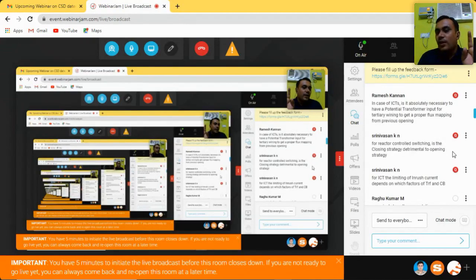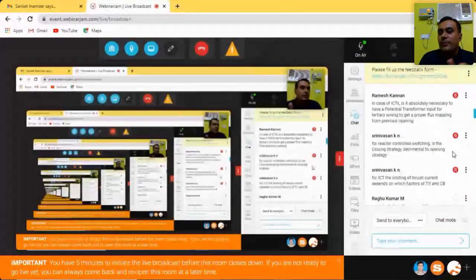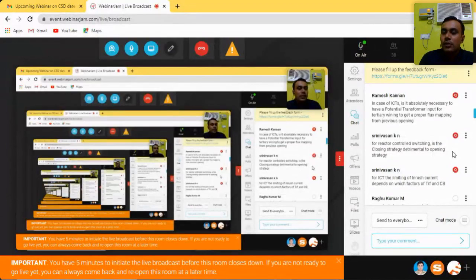And for opening we have two options, sir. We can synchronize the opening operation on voltage or current. For both operations the angle will be different, but we can open at the closing angle also. That will be for voltage reference, and we can open with current zero synchronization also. That angle will be 0, 120 and 60.